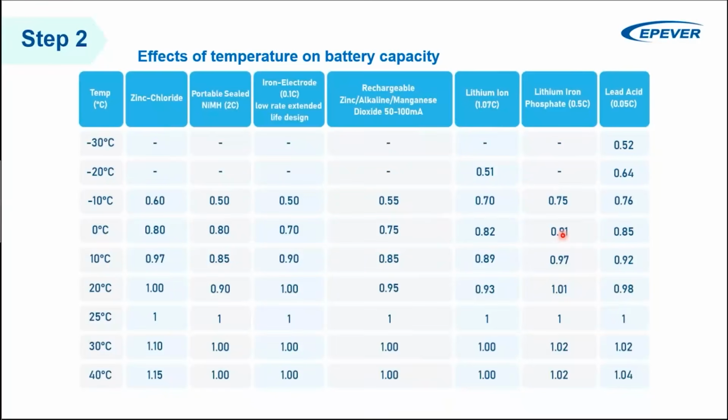Prolonged exposure to cold temperatures also has a big impact on the battery performance and the battery safety. When the temperature drops, the internal resistance of the battery increases. So batteries have internal resistances, and when it's cold, this resistance increases. What does this mean? It means that it requires more effort by the battery to charge, so they will not be charged with their full capacity.